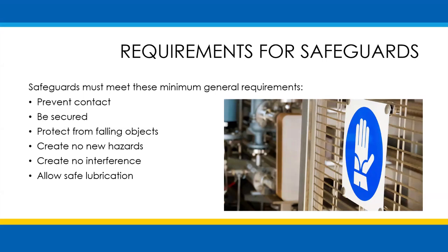A safeguard defeats its own purpose if it creates a hazard of its own, such as a shear point, a jagged edge, or an unfinished surface, which can cause a laceration. The edges of guards, for instance, should be rolled or bolted in such a way that they eliminate sharp edges.